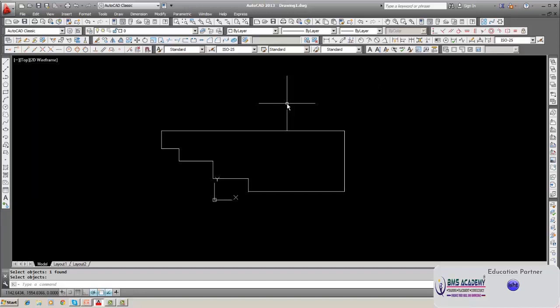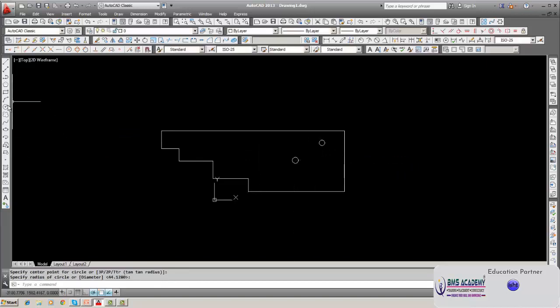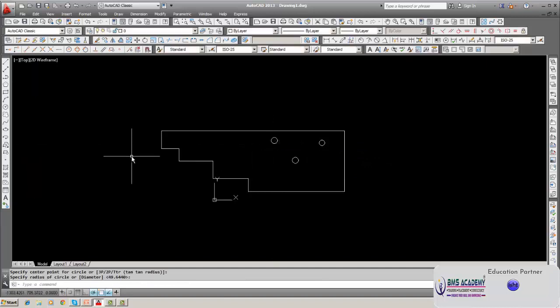See, many parts you are going to machine on a CNC machine. When you do CNC machining, then you need to have the coordinates of each point. Suppose this is a plate, and besides there are holes also inside, like this. 2-3 holes here, and you need to know the distances from one reference datum.